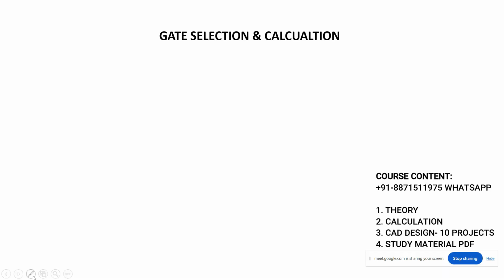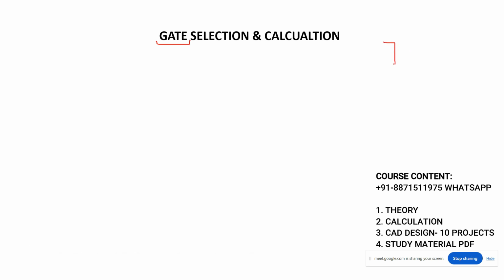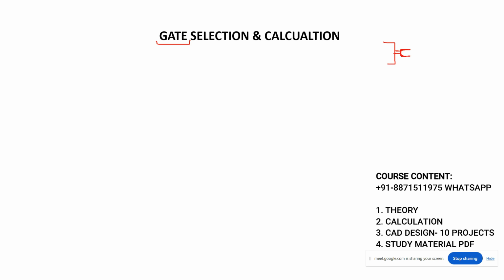What is the main definition of the gate? The passage for the part, yes, you can flow the material. So you can say that it basically exists between the component and the sub runner, or the main runner. So basically it will join this runner and the component together, right? And because of the gate, there is a mark on the component, right?